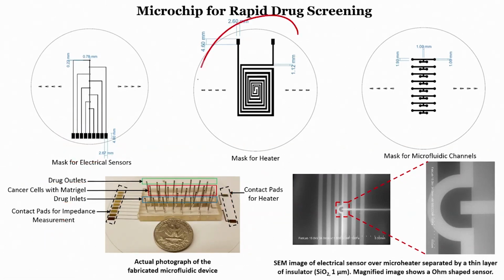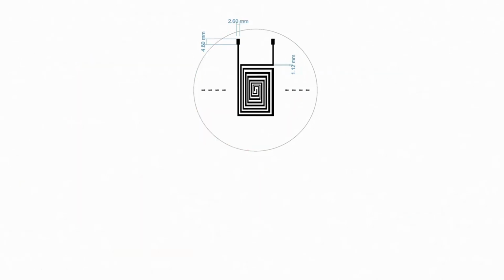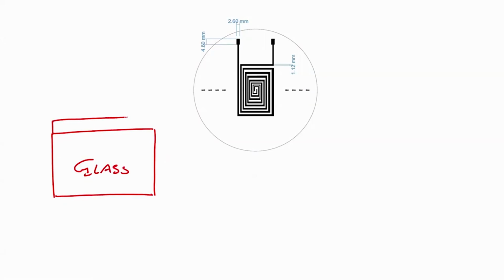First step is we have to fabricate a micro heater. Right. So, how can we fabricate a micro heater? Now, everything is on glass, right. So, we take a glass, and we deposit a metal for the micro heater. Let us say my metal is nichrome, right. So, I have deposited a metal which is nichrome for my heater.